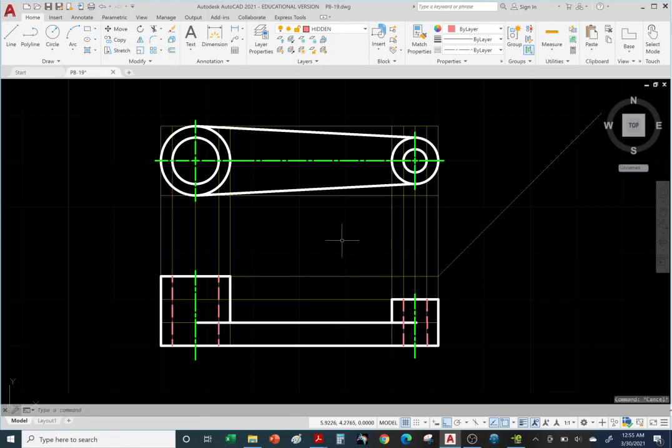All right, so for those of you that are wondering, hey, how do you change the gaps between the dashes? LTS, right? LTS. Not as easy as 1, 2, 3. So we can type in LTS if you want to play around with it. Maybe you want to increase the LTS. Go to the command line, LTS. And again, you wait till the very end.